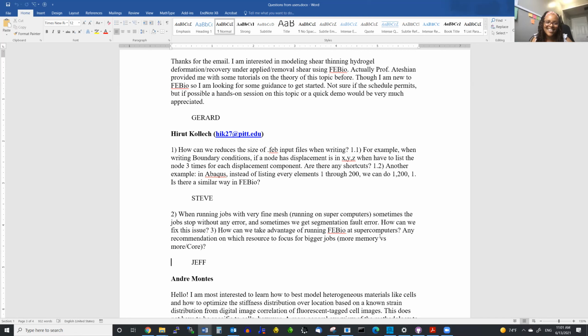No, it crashes when I open it. I just open the input file in a text editor. Yeah. Well, suffice it to say that the nodal data that you're looking for are probably in the plot file, unless they would need some calculations, for instance, in the post-processing side. But since you say that you can't open the model on the post-processing side, I'm assuming that's not a concern then. So yeah, I mean, you could in theory index into the plot file and find the same data.